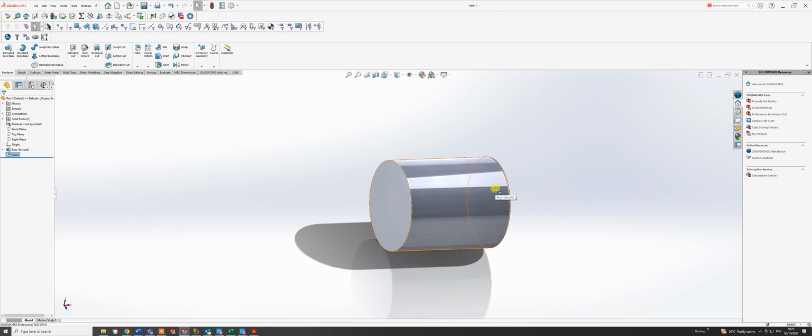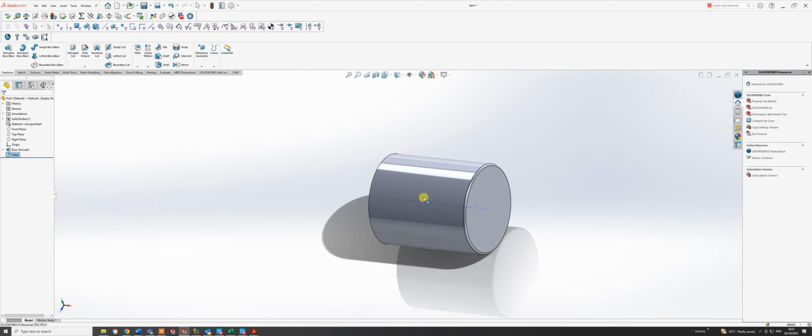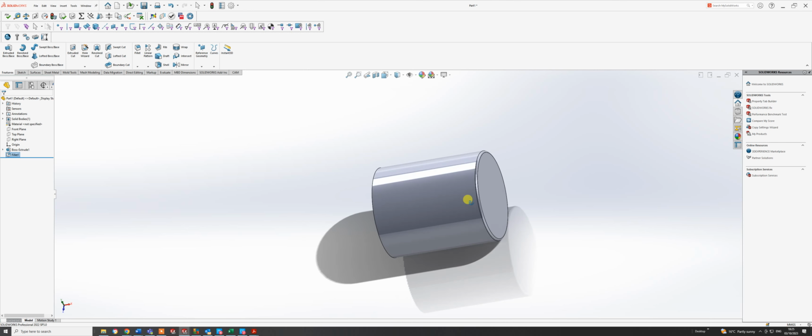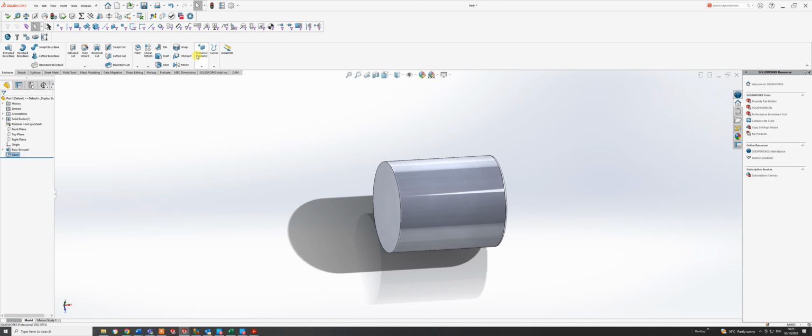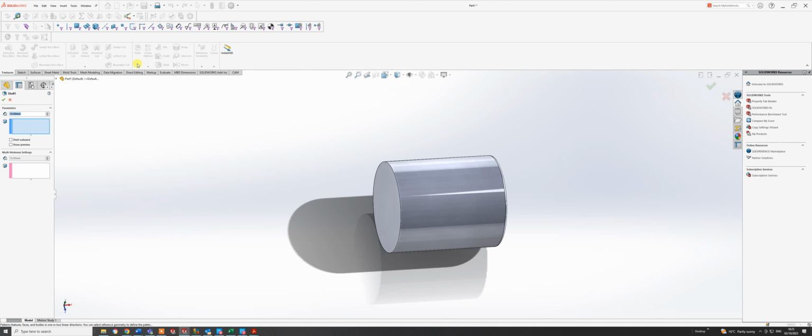Now you'll notice on the drawing at some point the actual thickness of the material that the housing is maintained in is approximately 0.3 of a millimeter. Now there's a nice little feature on SolidWorks that you can actually hollow that out, and it's called shell. So I'm going to go to shell. Okay, and it's another dialog box up here, and it's saying 10 there, but the wall thickness I'm looking at is 0.3 of a millimeter. So I'm just going to put 0.3.